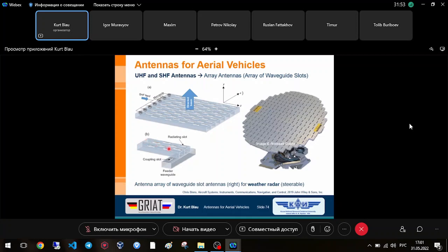This must be based on a very specialized mathematical routine. And for feeding these single waveguides with X slots, you can realize this with a feeder waveguide, which is perpendicular to these radiating waveguides, which consists of an antenna. And you can see this here as a complete arrangement, as a schematic, to understand how it works.